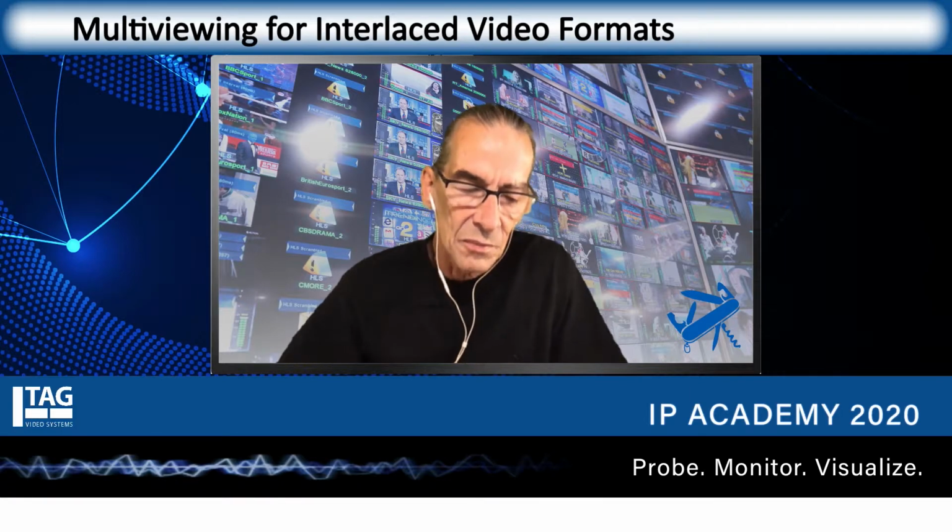It's interesting what you say, because of course in viewing and monitoring from a technical, creative content point of view, you want picture quality, you want to make pretty pictures. In multi-viewing, it's not intuitive, but you really don't want a fancy deinterlacer that hides things. You want a deinterlacer that cleanly deinterlaces but does no more, so you can accurately replicate what's really being conveyed in the signal. And so it's kind of counterintuitive, because we normally think of putting the best deinterlacing possible at every point in the system.